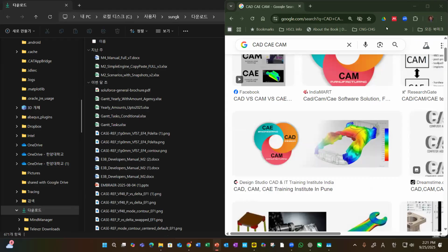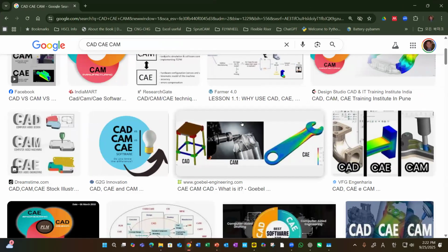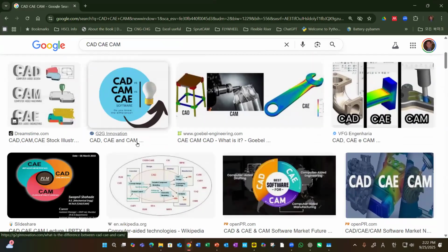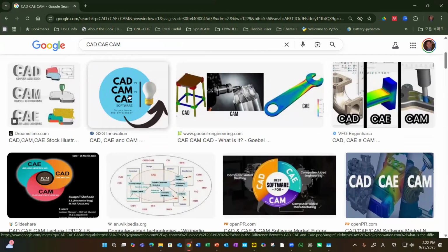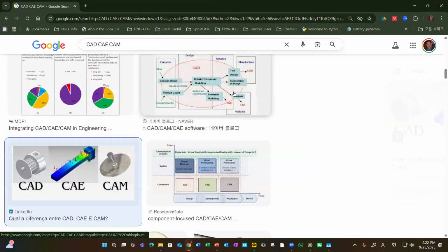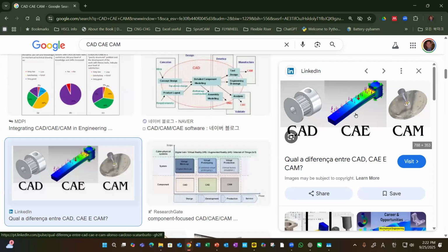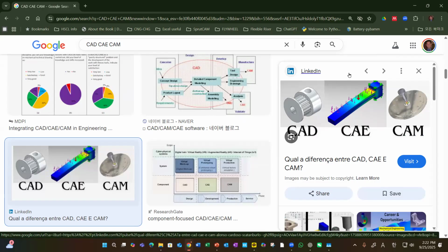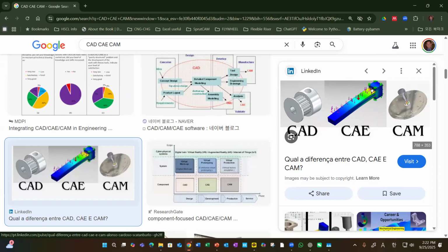Okay, that's why I know you guys didn't learn much about computer-aided engineering, but these are the tools. But more important, you understand the concept. CAD is always to visualize what you have, and with CAE you calculate the stresses inside, in a three-dimensional way or two-dimensional, giving us principal stress and boundaries, and then we can see whether this material fails or not. This is a hot spot we have to avoid.